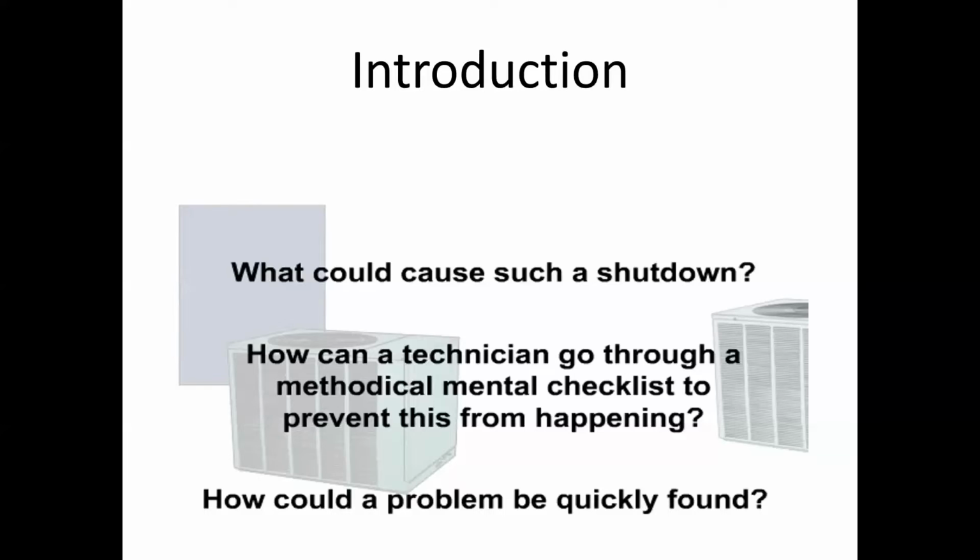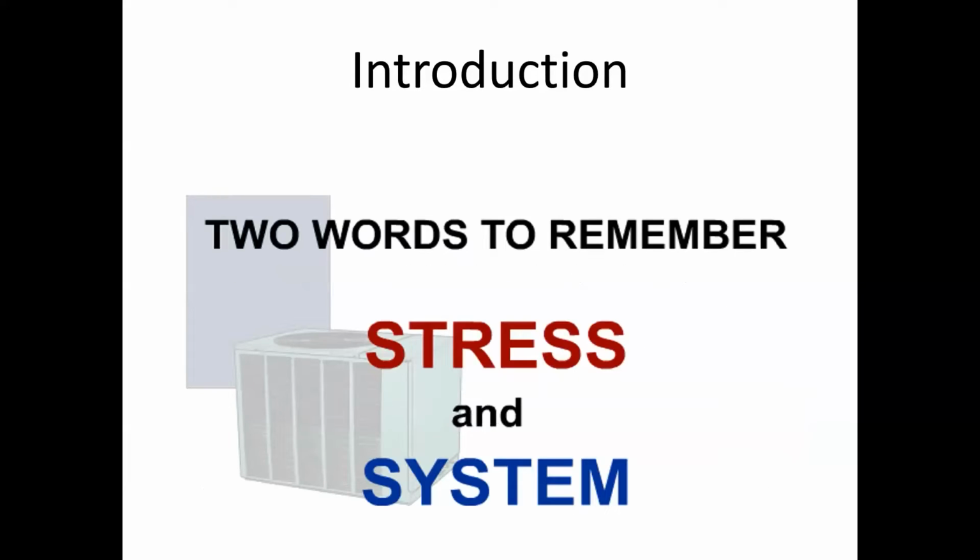This is something that I hear a lot about ECMs, right? That people keep having to replace indoor fan motors, and a lot of times that has to do with either moisture or airflow or both, right? It's not the motor that's failing, or the motor is failing, but it's because something is causing it, or the motor's being broken. We're breaking it down.